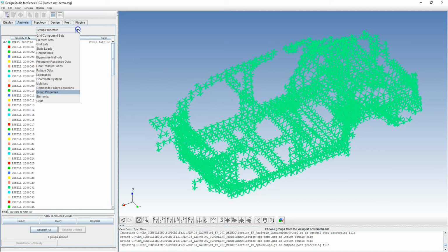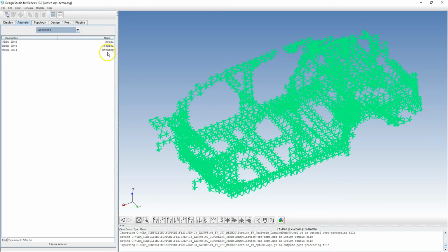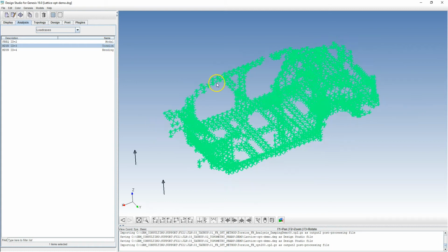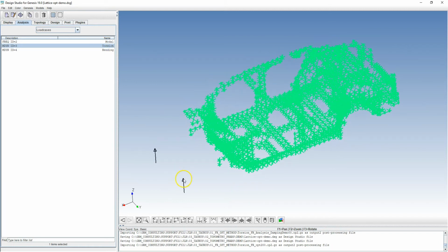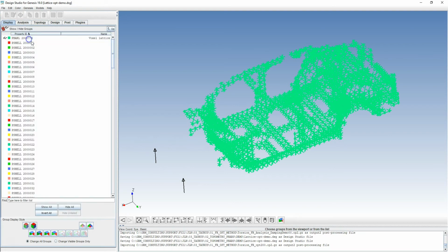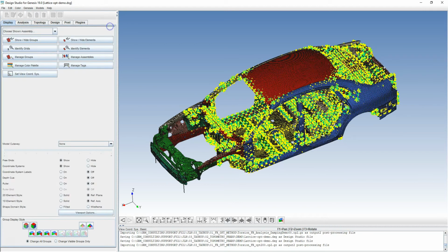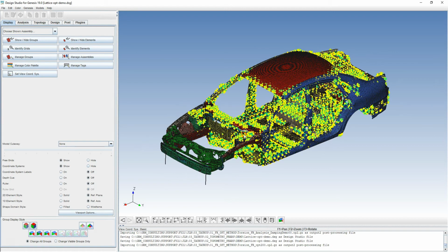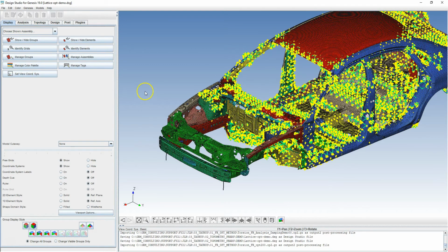Okay. So some other things just to note is the loading we've got in this model. And we're going to optimize for the torsional excitation. So we've got forces in positive, and this one, whilst it's viewed as positive, is actually out of phase by 180 degrees. So it's creating a torsion loading. And what we want to do is use frequency response to identify the first torsion mode.